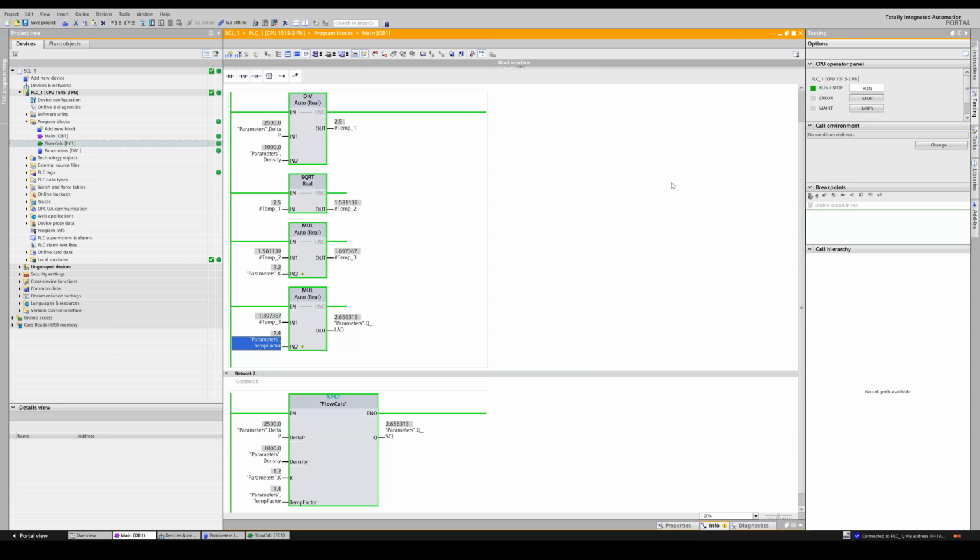In this video, you saw how a formula that takes multiple ladder networks can be written in one SCL line. In the next video, we'll look at all the basic math operators and functions in SCL. So basically, you will have a complete toolkit for any calculations you need.